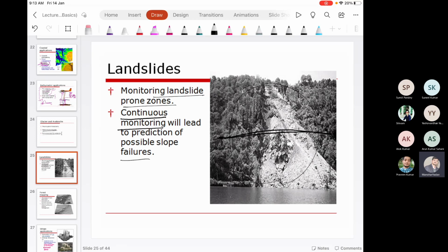If it is dense vegetation and we want to estimate the stability of slope, then first you need to extract the off-ground points. Ultimately you need to generate a digital elevation model, DEM. DEM is a representation of bare ground. So how do you get DEM?